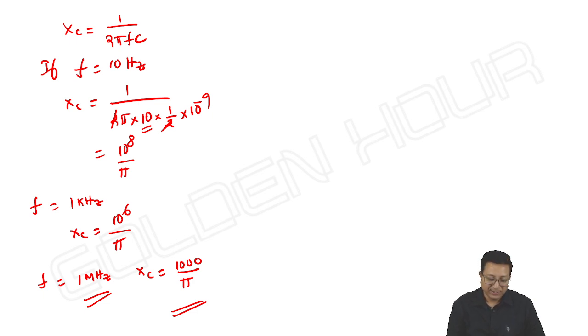So that's why impedance is extremely high at low frequencies, means it is considered as open circuit, and here also it is considered as open circuit. It is not short circuit, some appreciable value we can see. Okay, the effect of the junction capacitance can be seen at frequencies of megahertz, not in hertz or kilohertz.